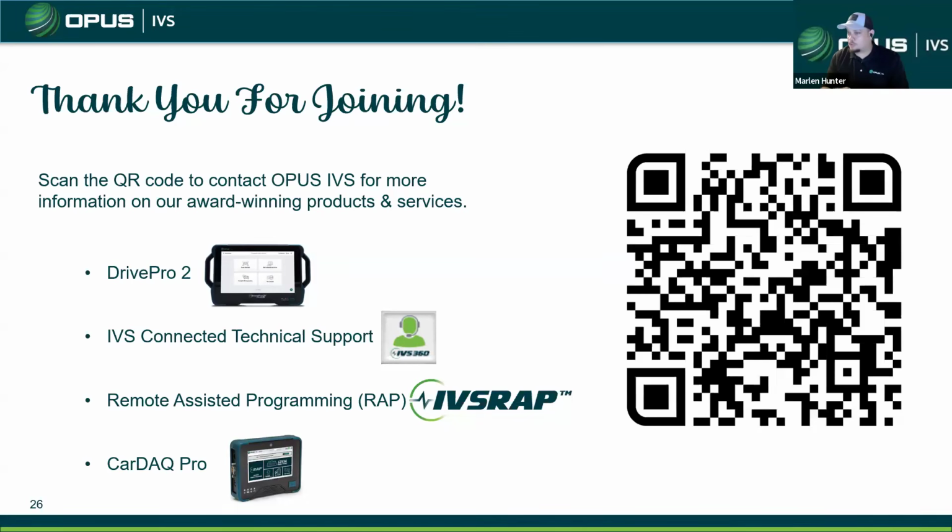And how often should you perform software updates when the vehicle states an update's available? This has been kind of, I wouldn't say a touchy subject, but there's times, I've done this myself, where I think, oh, there's an update, let me update it. But now not so much, because sometimes updates require a parts replacement. And if you look at Toyota, almost all of their service updates for software are related to a TSB. Whether that be for the Tundra, it tells you, hey, reflash the software for the camera. That's when you would want to do it.